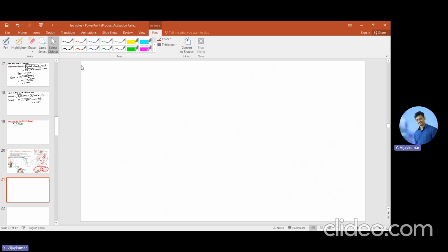During these three modes of operation, the voltage we call VQ max, we already discussed. As you know, in the first mode of operation it is going to be magnetized. In the second mode it is going to be demagnetized, which we also discussed. And there is the reflected voltage of the tertiary. How do we call this reflected voltage? NP by NT, the tertiary winding, into V1.